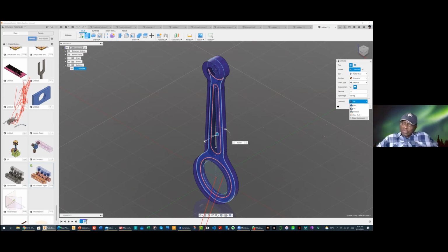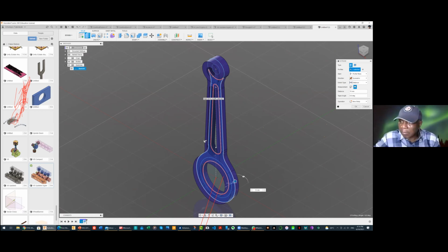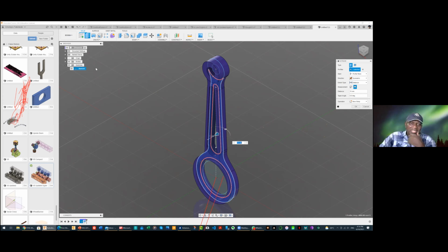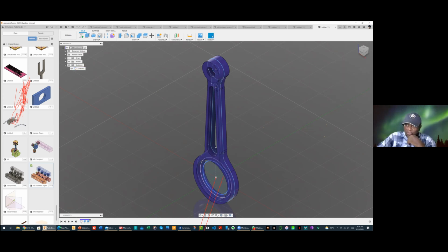So the last extrusion I'm going to do is the profile in here. So I do this extrusion here, and new body, I'll say okay. So the last extrusion is the inner circle here. So create extrude again. For the marking menu, repeat extrude. I want this extrude to be 30.